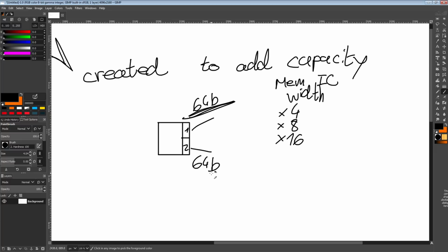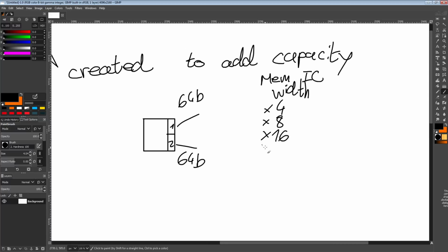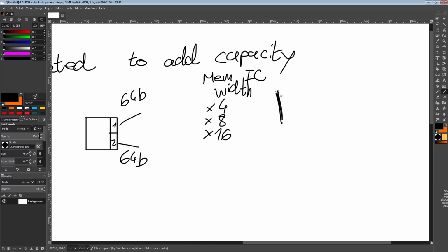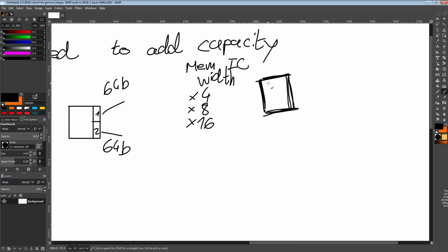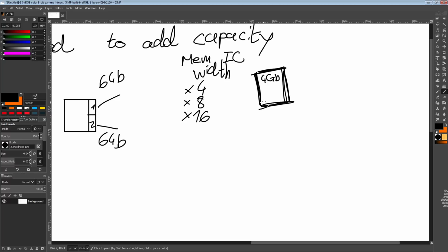And the problem with this is, of course, well, let's say we have this theoretical memory chip right here, and it's going to be 4 gigabits of capacity. For whatever reason, memory chip capacities are specified in gigabits, not gigabytes, but it just means that you need to divide the capacity by 8 to get bytes. Anyway, so 4 gigabit, and it's an X8 memory chip.